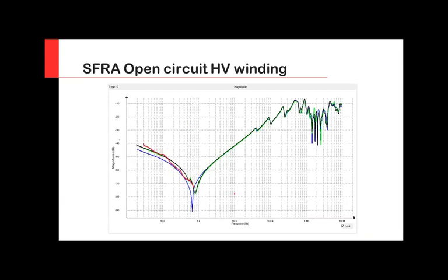You can see here symmetrical phases go basically one on top of the other. So very similar responses, and the non-symmetrical phase, as you can see here. And of course, we can clearly see where the first resonance, or what we call here the parallel resonance, or the current resonance, or the anti-resonance, is being shown. In this case, it's around minus 90 decibels.